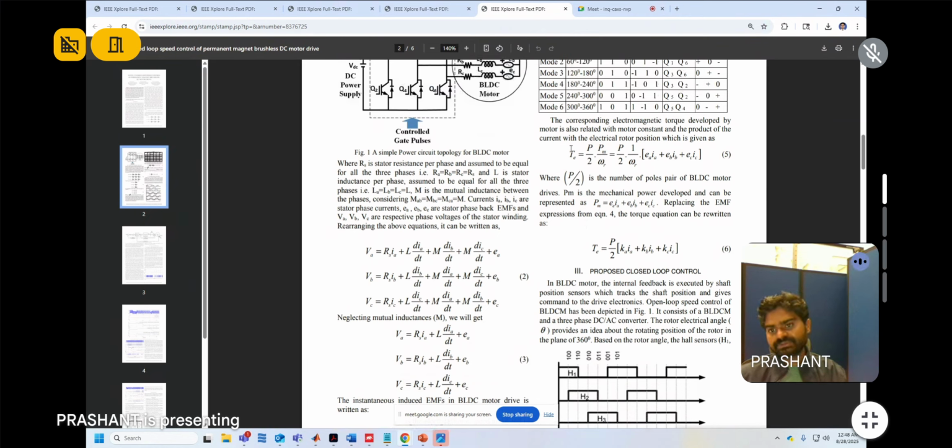Generally we know how the torque relation is obtained. So we have the voltage EA, IA, and then the number of poles and the mechanical speed. P by 2 is the number of pole pairs. Somewhere in equations you can see simply a small p, and we call it pole pairs or number of pole pairs, depending on the representation.